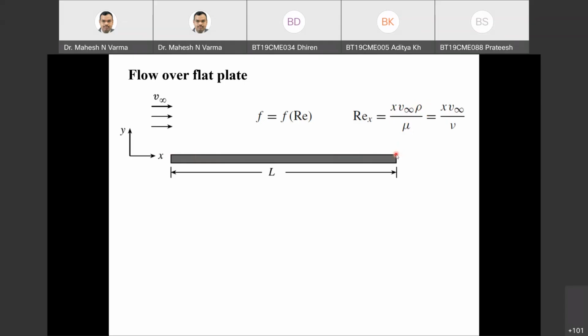Reynolds number is increasing. So what information do I have? Reynolds number less than 2100 is laminar, Reynolds number greater than 2100 is transient, and Reynolds number greater than 3000 is turbulent. That information will not hold here. That is for flow through pipe only. That is what you need to understand.